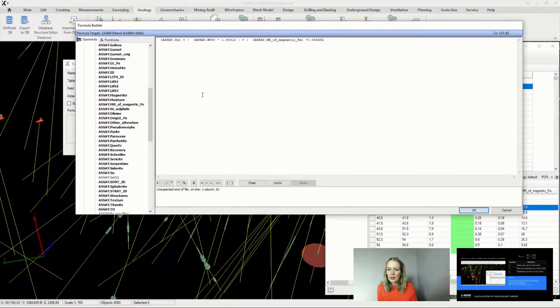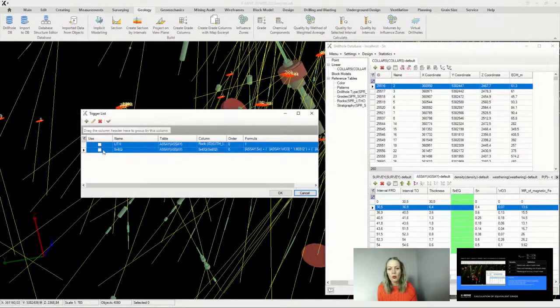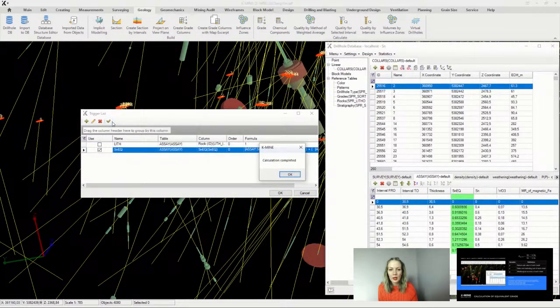With a trigger, we can assign drill hole intervals that meet certain criteria, like cutoff grade. That means that if the equivalent grade percentage is greater than or equal to 0.4%, then we enter code 1 in the grade column. If not, then code 2.